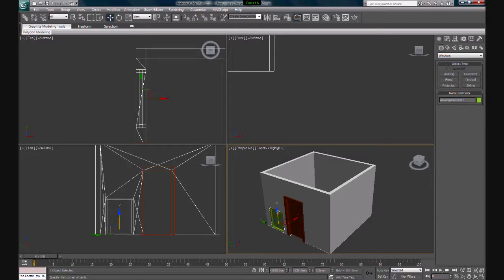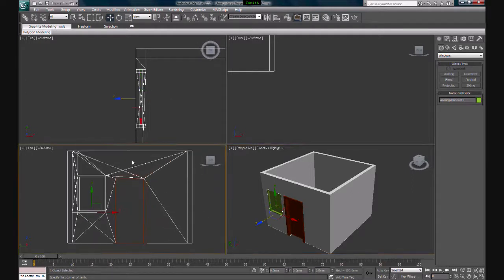Turn off the snaps so it won't get in the way. So now if you want to move the window according to the Z-axis, remember you can just click on the Z arrow and pull it up. It will automatically update the whole of the wall. Or if you want to move it according to a certain number, remember in the previous tutorial you need to click on this button right here where everything becomes 0 and key in the number. Let's say 1000, enter. Now you get it. So let's forget about these lines here. So far I don't know how to fix this up yet.